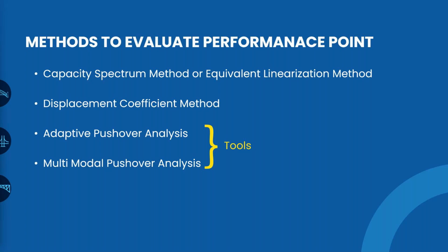In the case of pushover analysis, it could be an adaptive pushover analysis or a multimodal pushover analysis. The adaptive pushover analysis is a method in which the pushover analysis is carried out on a structure such that the loading pattern is modified in each step depending upon the type of deformation which is taking place and the plastic hinge formation in the structure at each location.